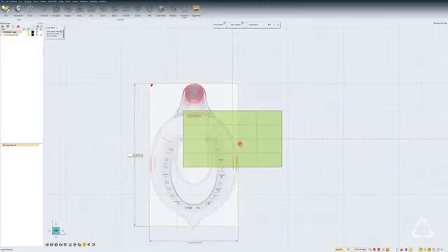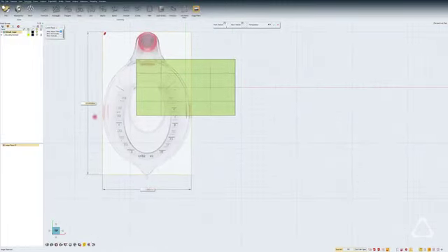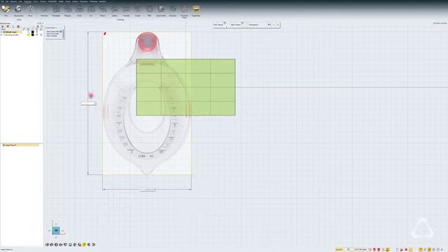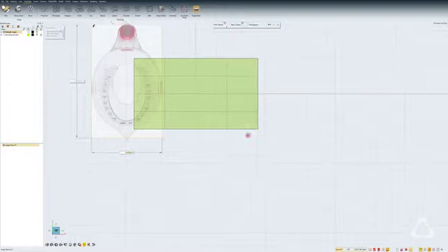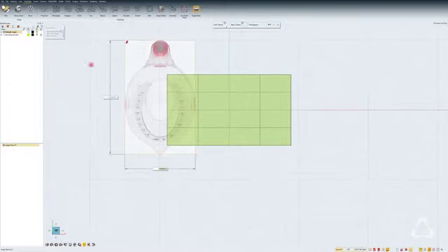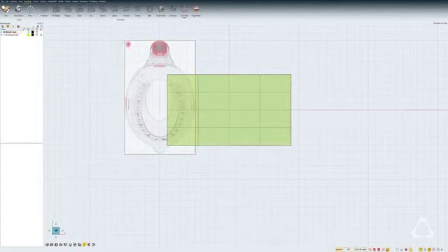It should open the image, and also you can see that the size is arbitrary right now, so we want to make the size 7 by 4. So this is going to be -7, and this would be 4. Since we have aspect ratio on, it's going to scale it evenly. Let's keep it at that and turn on mirror horizontal so that we can see the numbers and everything correctly. Hit the green check mark, and now the image plane is a regular object in your model browser.